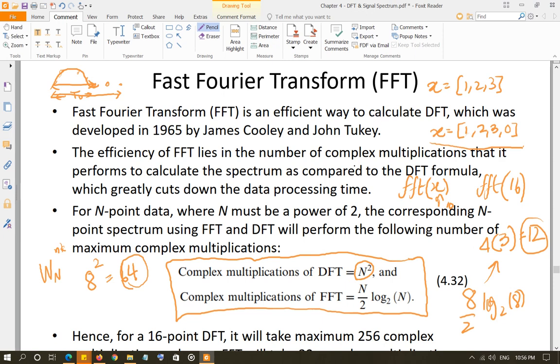So what will be the effect of t0 in the frequency domain? Remember, in the frequency domain, the total span of one cycle of samples is fs, the sampling frequency. That's one cycle. Now remember, ts did not change, so fs did not change.